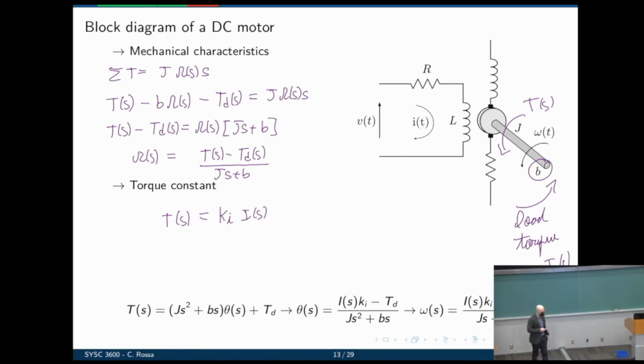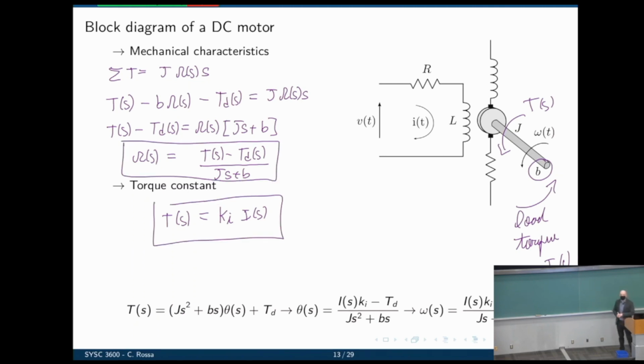Right. Well, the greater the current, the greater the magnetic field, the greater the interaction between the magnet in the rotor and the magnetic field, the greater the torque there. So current now influences the torque, while speed influences the back EMF voltage in the armature. So now I have a set of 4 equations to work from. And let's put them together and create a block diagram to represent them.